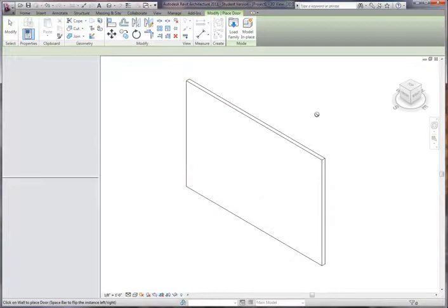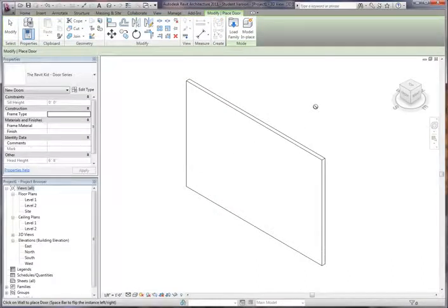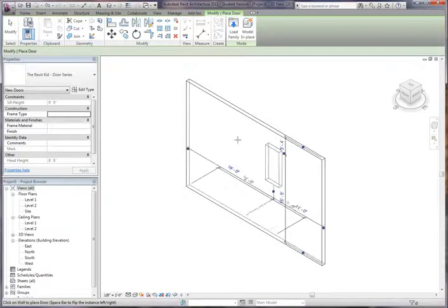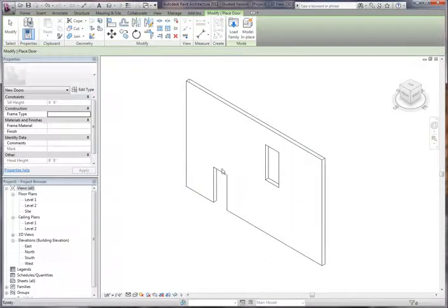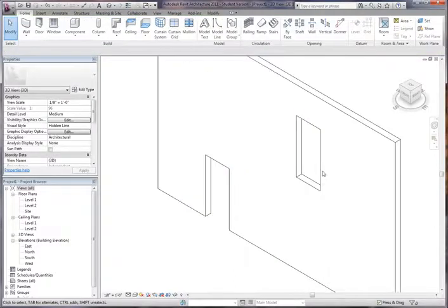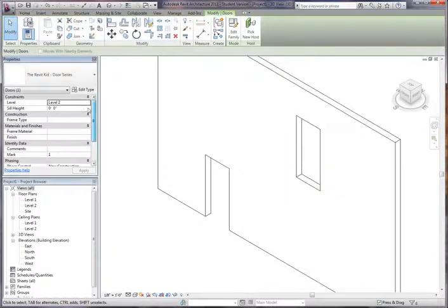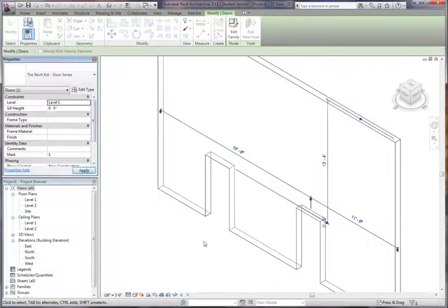And you can see it automatically hosts to a door. If I'm outside of a wall, it will not. It'll give me the no and I can't click it. If I go to the wall, you see it pulls it up. So if I click here, it's actually putting it on the second floor, that one's putting it on the first floor. So this one's actually, if you select this door now, it's hosted to level 2. So we can just bring that down if we want.